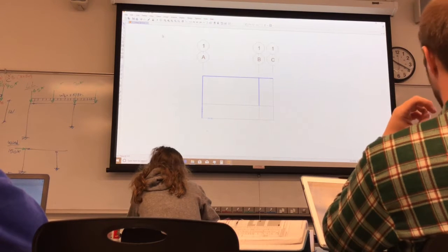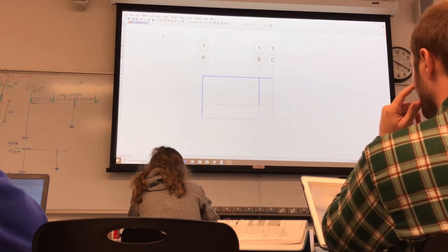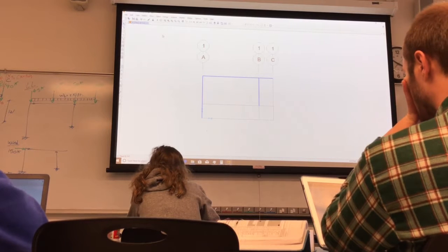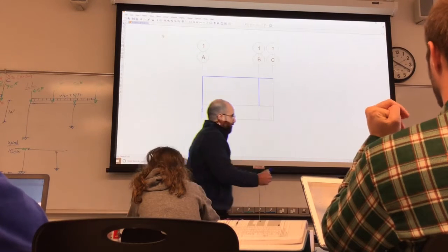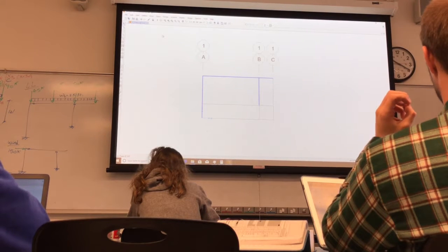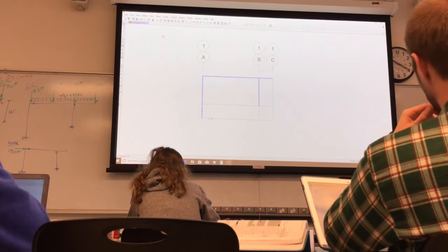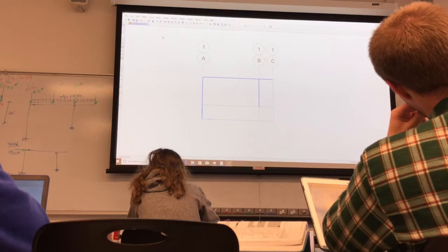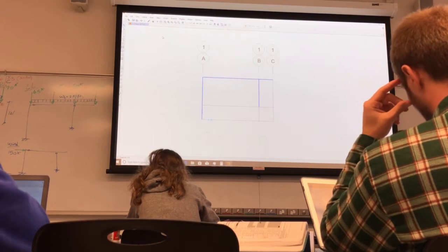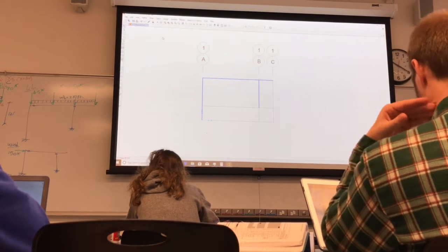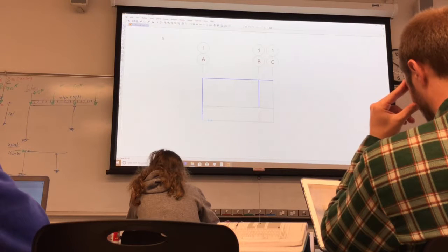Why do you model the top beam as two separate? Yeah, you have to, because that's a finite element question. That's a good question. If you don't put a node here, then the software is not going to understand. See, the computers are not smart, right? So the software is not going to understand that this column is carrying the beam.